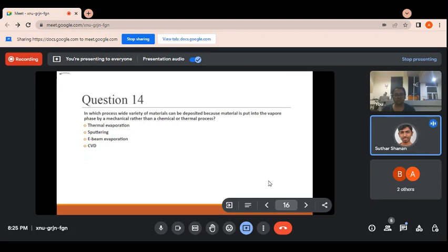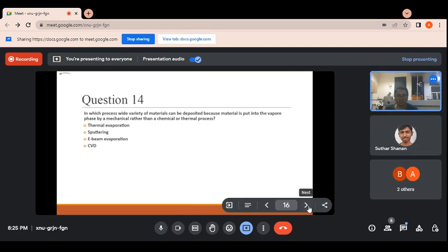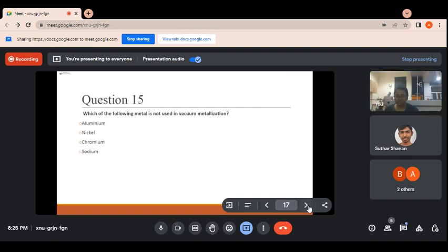In thermal, the material is limited because the source holder can't withstand materials with a high temperature, right? Actually, here argon ions are sputtered on the target material, which is the source material we want to deposit. It comes out from this target and is deposited on the substrate. Okay, yes, so the right answer is this. Banala Sindhu, have you got the answer? Yes, ma'am.